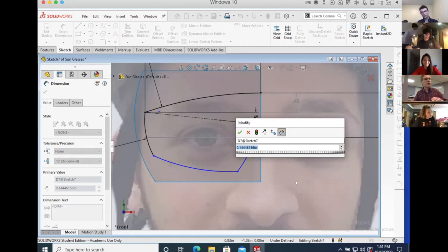When people are using spline curves, they have a tendency to use too many control points. The more control points you have, the less control you have. So fewer control points. If you're doing a loft with a whole bunch of cross sections, the fewer cross sections you need to use, the better.